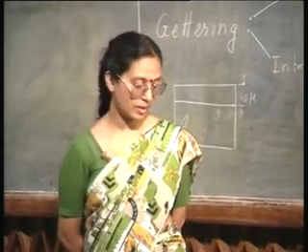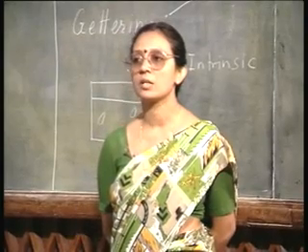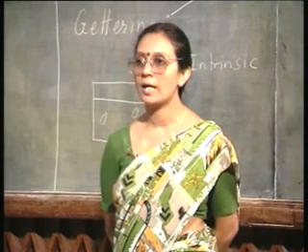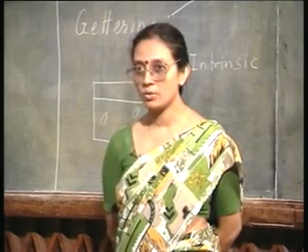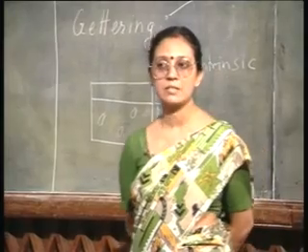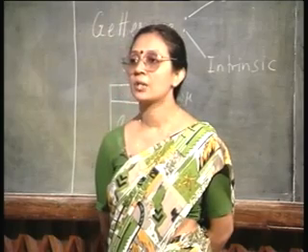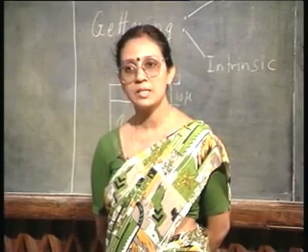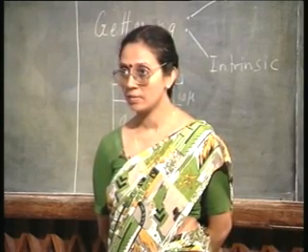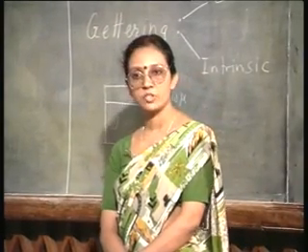For example, think about your bipolar junction transistor. In order to make an NPN transistor, we started out with a p-type substrate, and then after the buried layer diffusion, we had to carry out an epitaxy in order to have the N region grown on top of the p-type bulk crystal, and the actual device was housed in this epitaxial portion, not in the bulk crystal. Remember? So, just having this bulk crystal may not be sufficient for your needs.